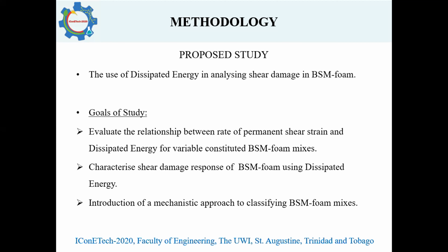The goals of the study are to evaluate the relationship between rate of permanent shear strain and dissipated energy for variable constituted BSM mixes, to characterize the shear damage response of bitumen stabilized mixes using dissipated energy, and to allow for introduction of a more mechanistic approach to classifying these mixes.